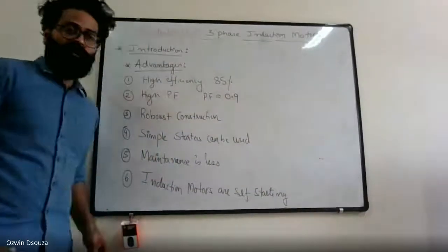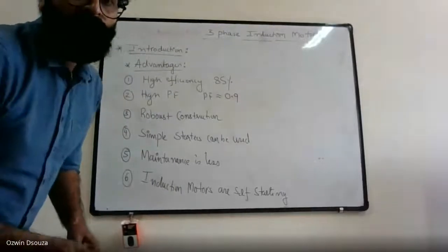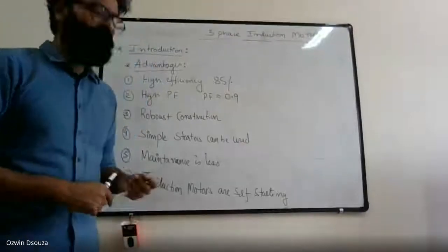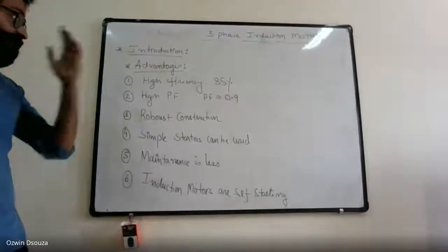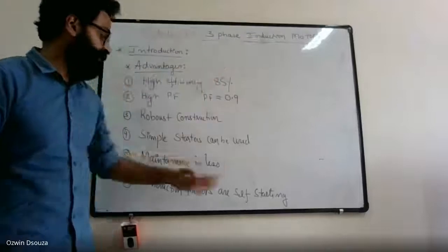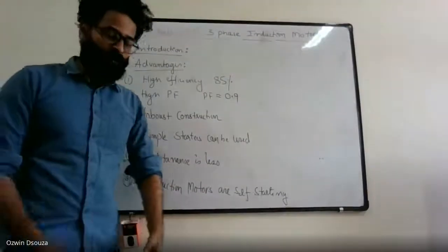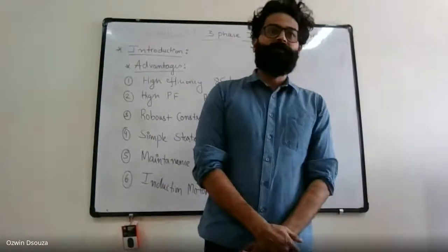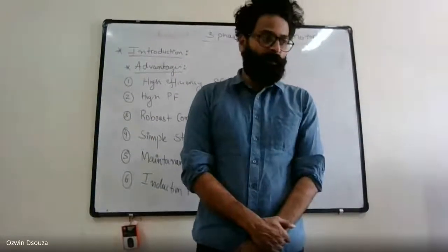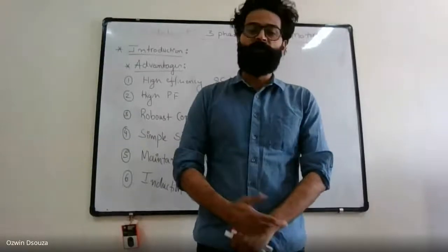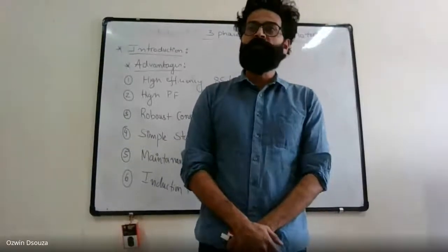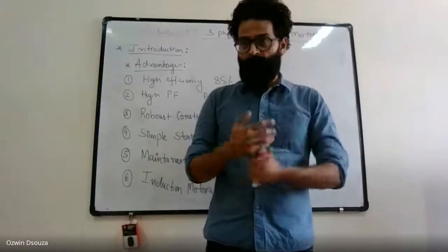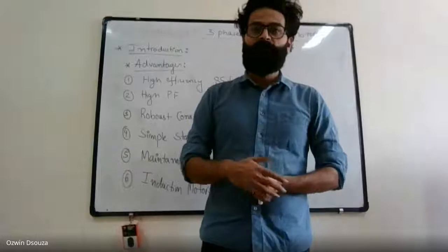Induction motors are self-starting. In a sense, the moment when you connect three-phase AC supply to an induction motor, the motor starts to rotate, which is not true for a synchronous motor. So the moment when you connect AC power supply to a three-phase synchronous motor, the synchronous motor will not start, unless you provide some auxiliary starting mechanism.